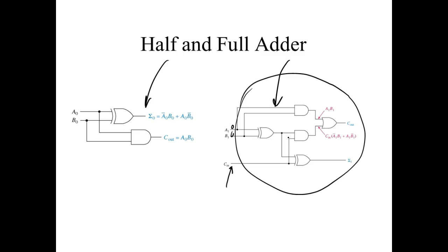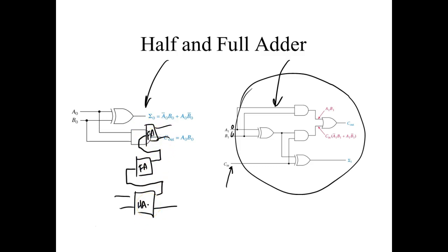That makes sense? So a half adder, what it will do, it'll add two binary bits and it'll generate a carry, but then we got to come up with another circuit that would take the carry. Does that make sense? So down here, I would bring in two numbers, and then this would be a half adder, and then this would generate a what? This would generate an answer for this bit, and this would generate a carry, and then I would bring this into a what? A full adder. This would generate a carry, and then I would generate a full adder. So you'd use a half adder on your least significant bit, and then from then on you'd use full adders, and then we could come up with a way to add binary numbers.